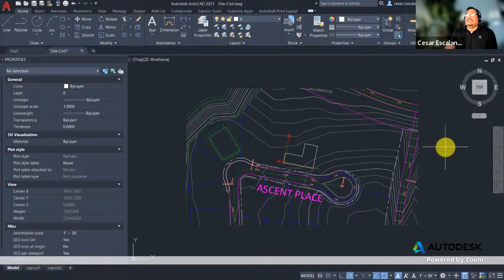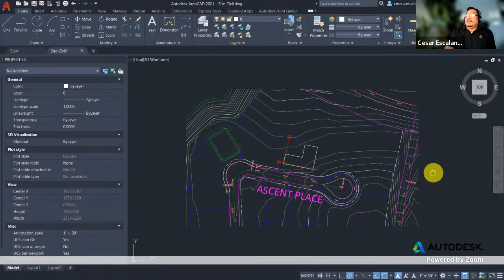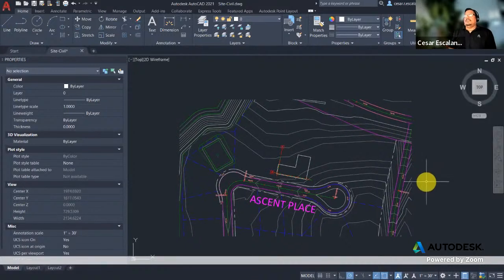Just before you send it to me, can you re-export it? And in the process of re-exporting it, you also get rid of all these extra pieces of information or extra layers that you might not need. The thing is that architects don't know what to ask. And so once you know that things like this are easy to ask, it helps the coordination.